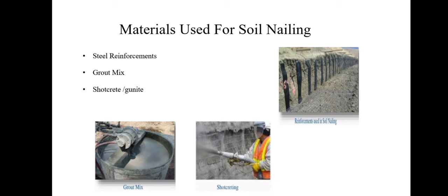So, what is shotcrete? Shotcrete is basically a mixture of aggregate and Portland cement conveyed by compressed air to the nozzle of a spray gun where water is added. This is a wet mixture which is sprayed in place and may be carved or troweled almost immediately.